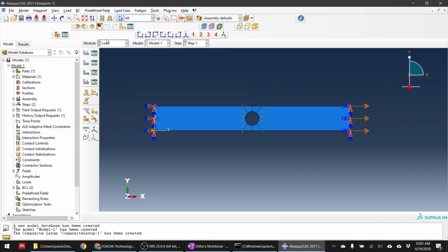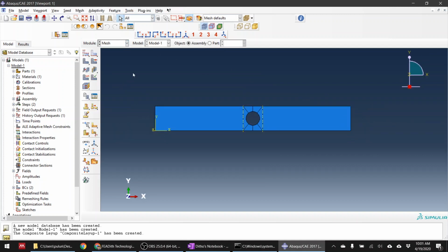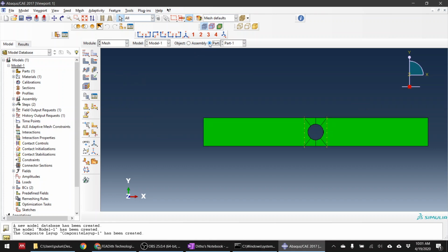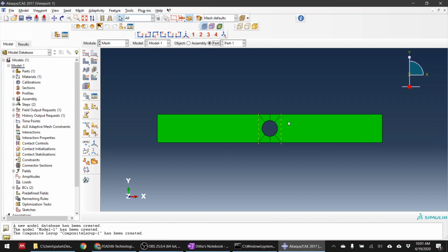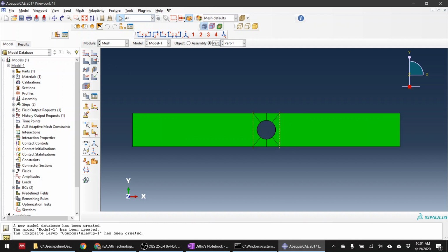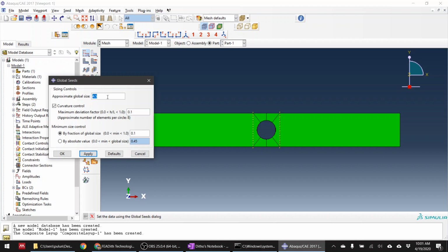Right, you pull it there, and then the most important part is this part. Make sure you click part here. See, it's now all green. Green means that you can use a structured mesh here. So I'm going to show you what happens if you don't do proper stacking direction. So I will just leave it like this and click here. I will just put 2,